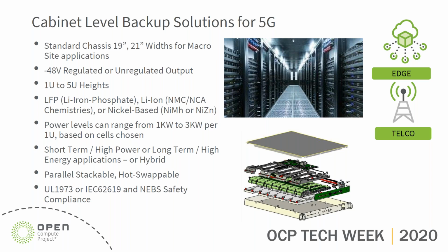And what we're also seeing, interestingly enough, from a couple of companies is they're saying, well, I'm really not yet ready to jump over to lithium ion. So what do you have in between? We've been involved with a couple of design discussions around some of the nickel-based solutions, which some say, well, that's older technology, nickel metal hydride or nickel zinc. But at the same time, it does give better energy density and more modularity than steel lead acid, but it just doesn't give the same energy density as you can get with lithium ion. So just different options that are out there. And again, parallel stackable, hot swappable, et cetera, same safety certifications.